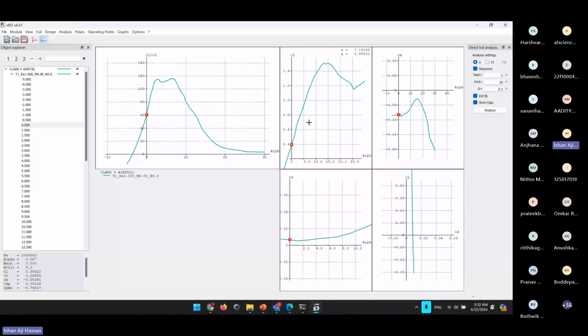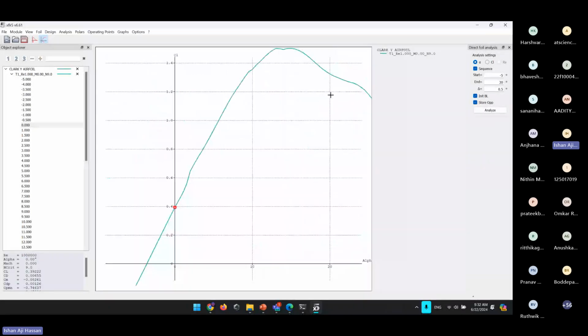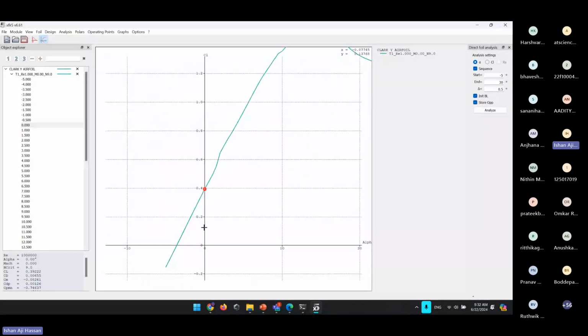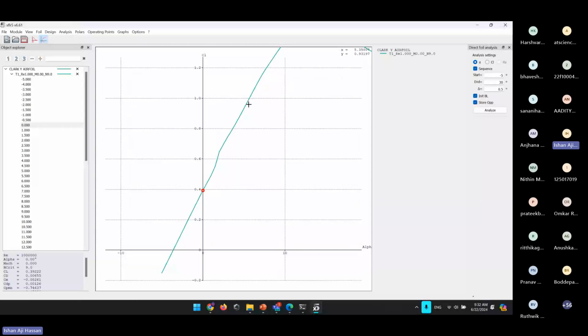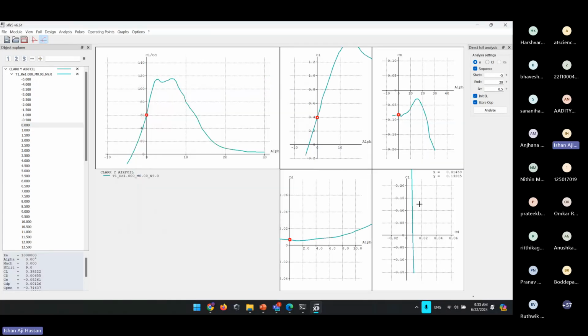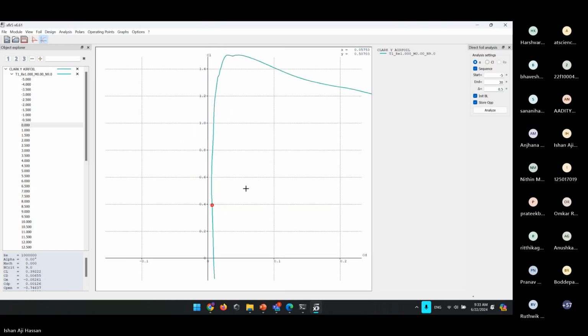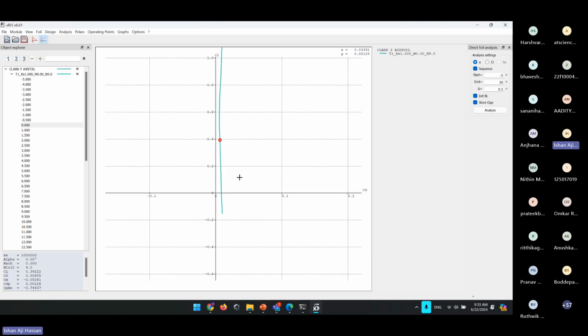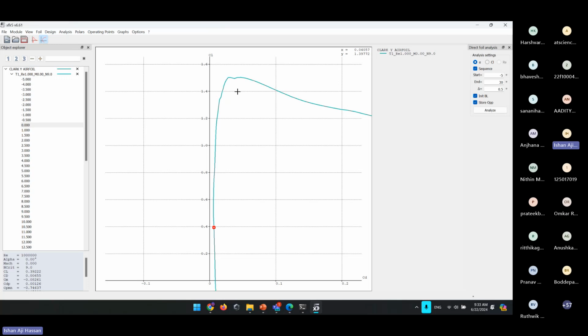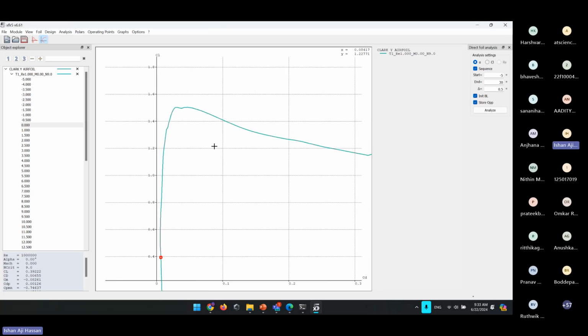And if you look at the CL graph, what you can see is that from -5 to 7 degrees almost, that is almost this entire range. And you can see that over that range, CL varies over such a large distance, like around -0.2 to 1 or so at 7 degrees. So that is why there's such a large range of CLs for the particular CD of 0.01. So that is this sharp rise that we see. If you see, the CL goes from -0.2 almost to 1, 1.2.